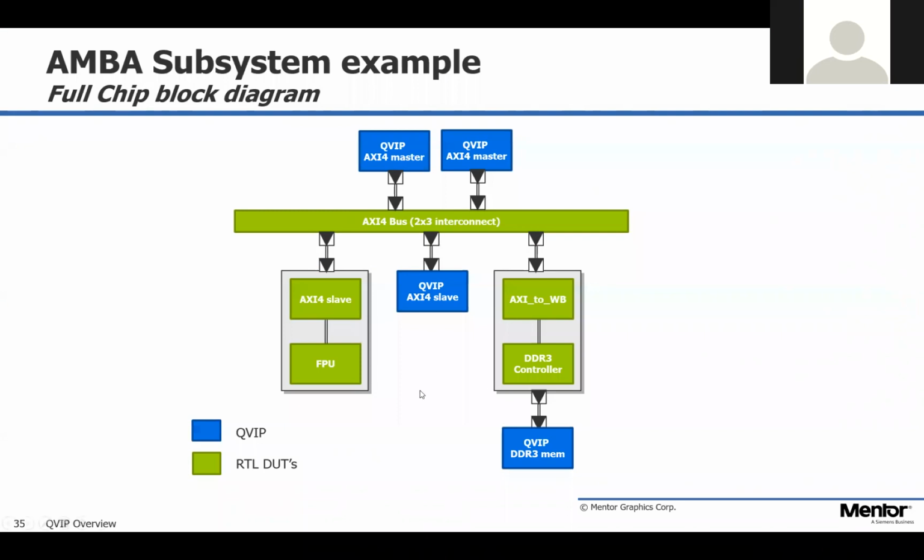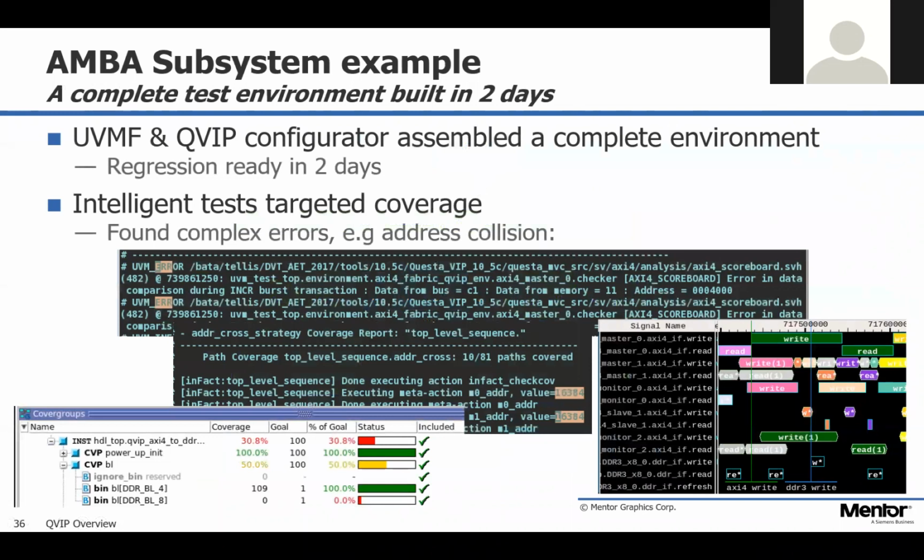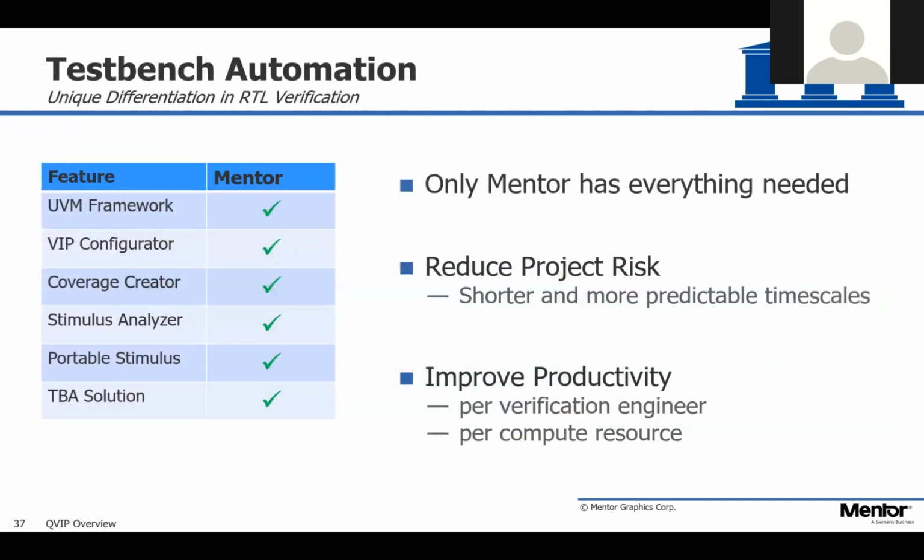This is just an example. I had a particular DUT here that had a floating point unit. I had these AXI things, and I was able to completely use VIP components to hook up to all the external ports of that, and run that through the generator and start generating traffic quite quickly. So our verification IP works with the UVMF generator.